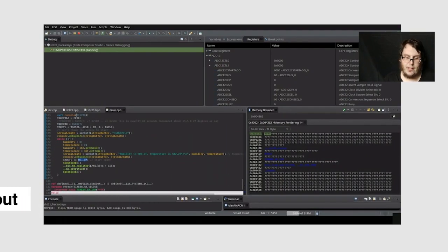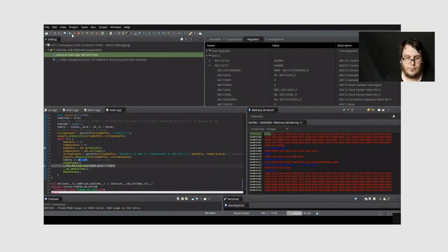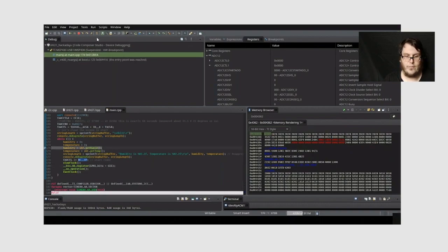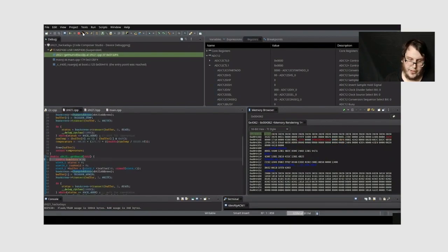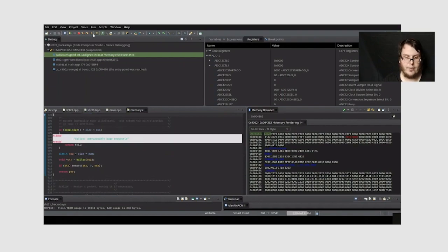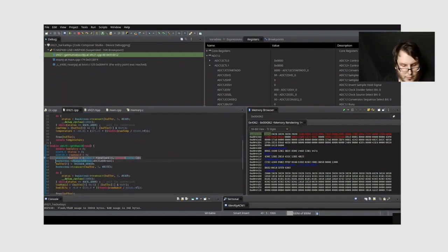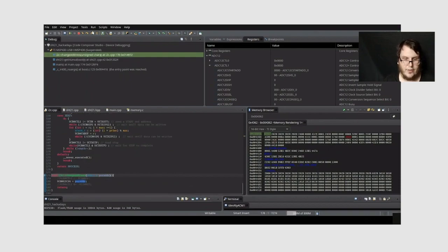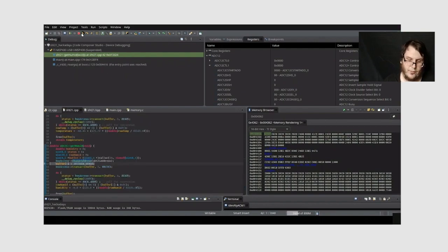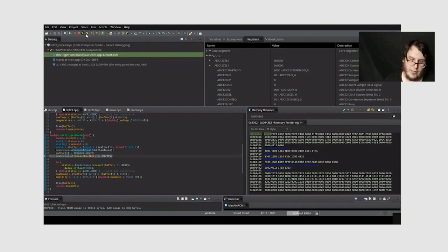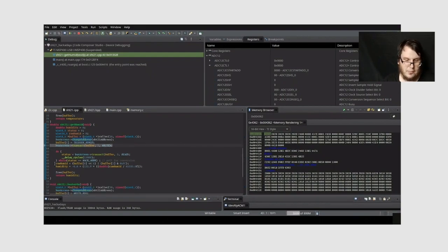code. If we pause, we can have it break when we go to get the humidity. Now we can go through this if we want. See it go through. Oh yeah, step out of that. What we want to see is this. Of course it changes the address, so it calls that function down here to change the address. It sets that register to the correct address. We go back. It loads the buffer with that humidity trigger, and then we'll just skip ahead.